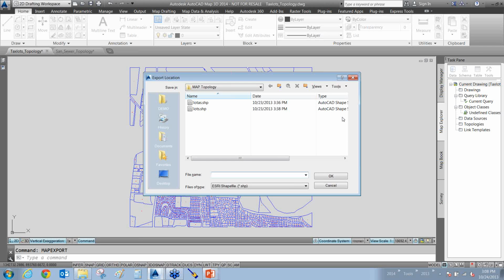Those of you on 2014, specifically those of you who have Civil 3D 2014, or better yet, the Infrastructure Design Suite 2014, well, if you have not loaded up any service packs, then get out there and do so. The reason I'm saying this is because there are several commands inside of Map, and even a couple inside of Civil 3D, and even a couple inside of AutoCAD that are broken because of things like the Civil Object Enabler.